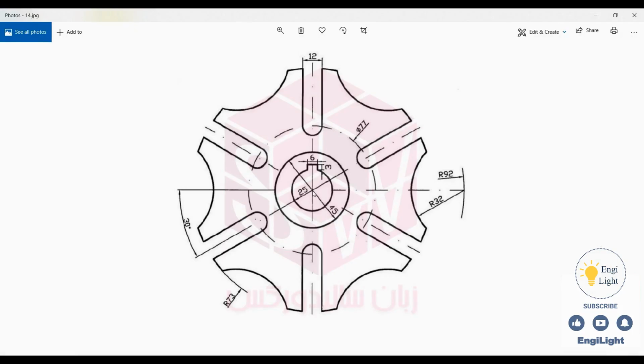To draw this sketch, I'll start by creating a circle with a diameter of 25 millimeters. Then, I'll create another circle with the same center and a diameter of 45 millimeters. I'll place the origin here. Then I'll create a larger circle with a radius of 73 millimeters. And finally, I'll create this shape, and then this one, followed by a circular pattern from them.